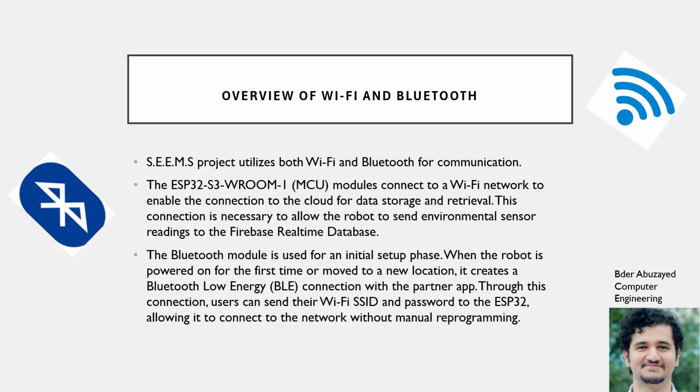The communication between the Sentry and the mobile app will require a means to establish a connection between them. The Wi-Fi module will connect our microcontroller to Firebase to send the sensor information and retrieve it. On the other hand, the Bluetooth module will be a one-time-use setup to send the Wi-Fi credentials to the central robot to connect the module to the internet.